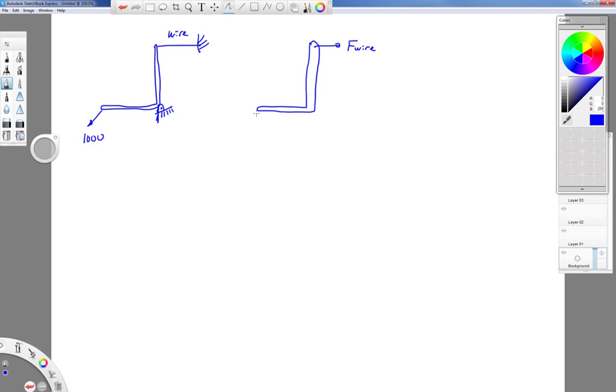And as this gets pulled down this way, off at some angle, let's call that angle alpha, then we would introduce tension in that wire. And then typically what we would do is have 2 forces as a horizontal and vertical reaction at the pin. Maybe that's position B, so we'd have a force BY and a force BX.